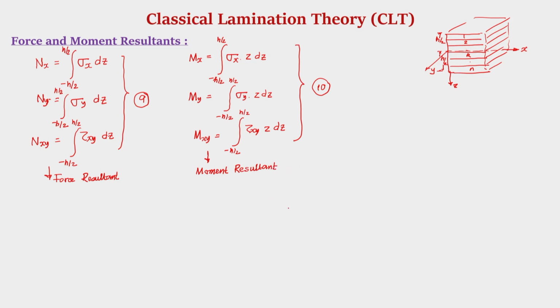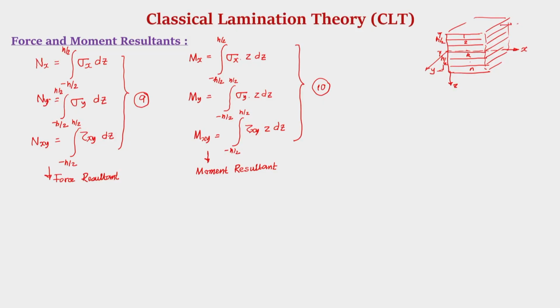Please try to understand what we have done here. In each layer there are stresses. So, we have actually replaced those stresses in each layer by means of an equivalent force and an equivalent moment, which is actually acting at the mid plane. Say, this is sigma 1, and please try to understand that sigma 1 is not only one component, it is actually all the 3 components of stresses, sigma x, sigma y and so on. Here it is sigma 2, like this, and here it is sigma n.